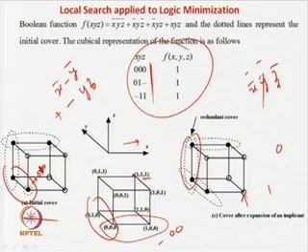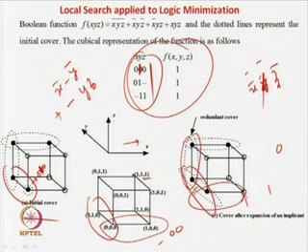You may also not start with the set of prime implicants; you can directly start with this function set also, that is also possible. Okay. So, in this case you find the 3 primes, you start with this one, then you start eliminating one literal from any of the terms. You can start with anything, for example x prime, and you find it does not become a valid solution, because it becomes this way. Then you start eliminating y prime. If you eliminate y prime, then your solution will look like this. Okay, and then you can find that this becomes redundant and it can be removed.